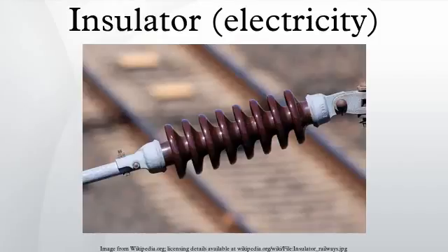Class 1 and Class 2 insulation. All portable or handheld electrical devices are insulated to protect their user from harmful shock. Class 1 insulation requires that the metal body and other exposed metal parts of the device are connected to earth via a grounding wire that is earthed at the main service panel, but only needs basic insulation on the conductors. This equipment needs an extra pin on the power plug for the grounding connection.